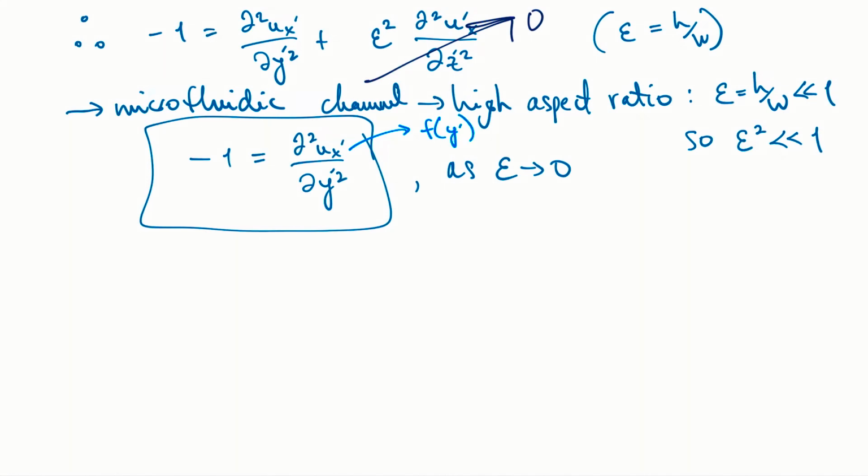And what we've done here, in simplifying this, is we scaled our ux because we were looking for the dominant terms in this equation. So our strategy for this first part of the question was to say, how do we simplify this equation? And it was essentially saying, look, we have this geometry, we have these approximations, low Reynolds number, and we can get this in the simplest form possible before we try to solve it. That's what our goal has been up until now. So let's go back and redo this without the characteristic velocity, for example.